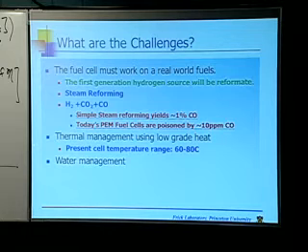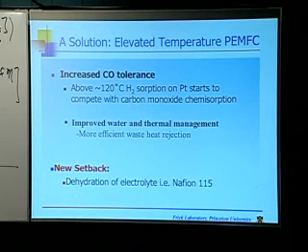So if you could do something about the thermal management, that would be nice. And while you're at it, I've already mentioned this water management issue. Electrodes dry, membrane wet. If you could do something that would make that easier to manage, go ahead. So you solve all three of those problems and do it cheaply, and you can sell it to me. Yeah. CO poisoning, does it help by going up in temperature or hurt? So, boy, this guy, he goes and he steals your punchline. The answer is simple. All three of those are fixed by going up in temperature.